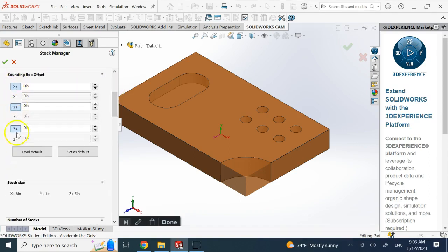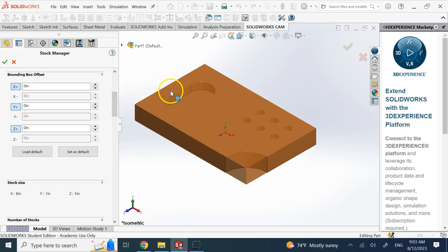And the other thing you can do here is add to the thickness of the stock part in different directions, right? For example, if your stock on the top surface is not really properly finished and it's a rough top surface, then you want to add something to the Y thickness, and then let this top face be face machined, right? Face milled.